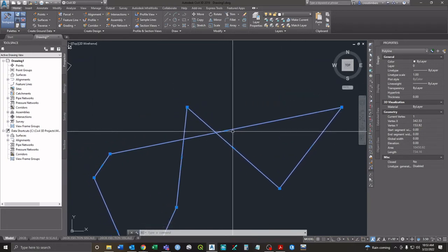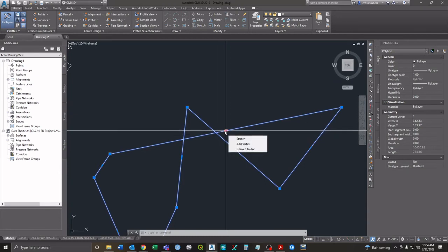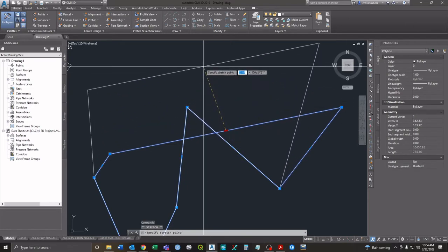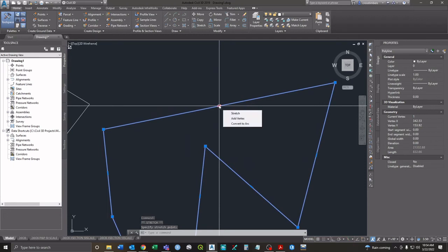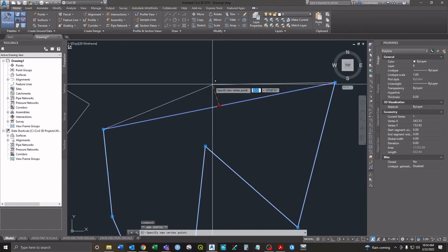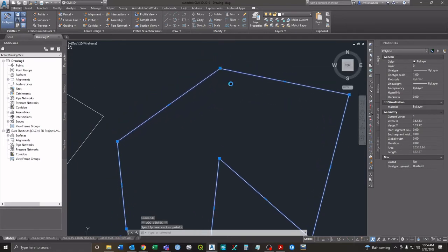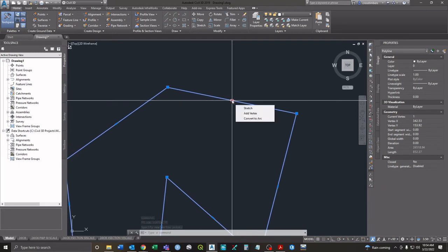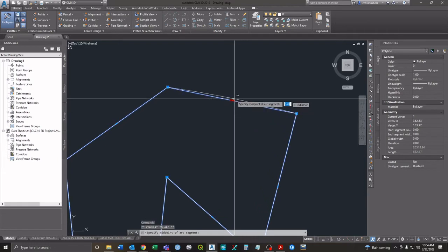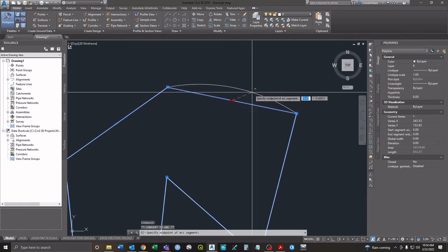Okay, but you notice the difference in the middle one, it's flat, so there's different options. So you can stretch it and move the whole segment up, same kind of as a line. We can add a vertex, which basically will change this point into a vertex, right? Or the other thing we can do, which is not necessarily something you'll need to know, but you can convert it to an arc, which we haven't talked about, but now you can see how it's an arc function.